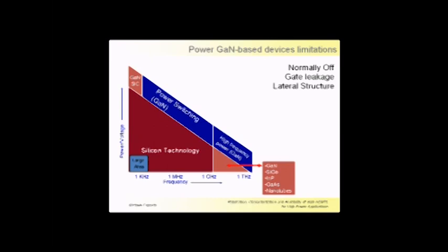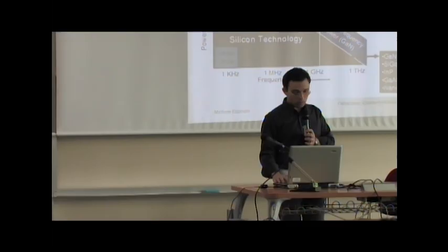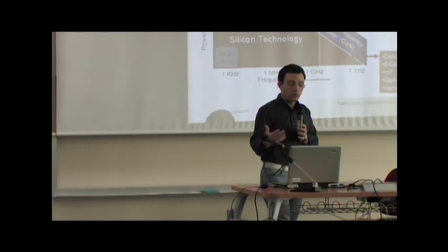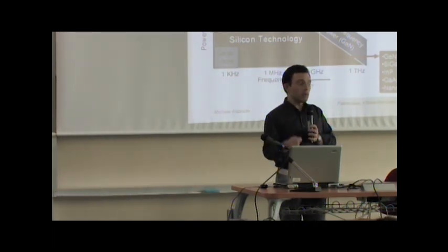Usually power devices are vertical devices, so the applied voltage spreads across a thick bulk material, but not in our case. In our case, we have a lateral device. Plus, we have to deal with some thermal dissipation issues due to the substrates.